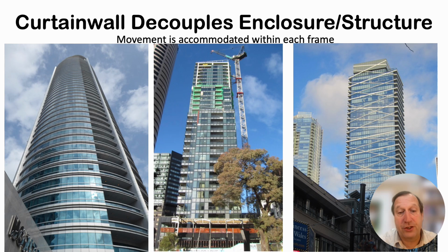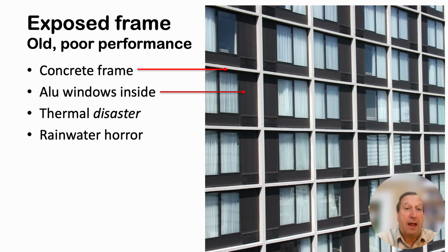The normal system can accommodate maybe 12 millimeters or half an inch to 3/4 inch of movement, and then you have to start going to specialty frames. Now, this is an example where the tubes in the form of windows were installed between, not outside of the superstructure, but within the superstructure.